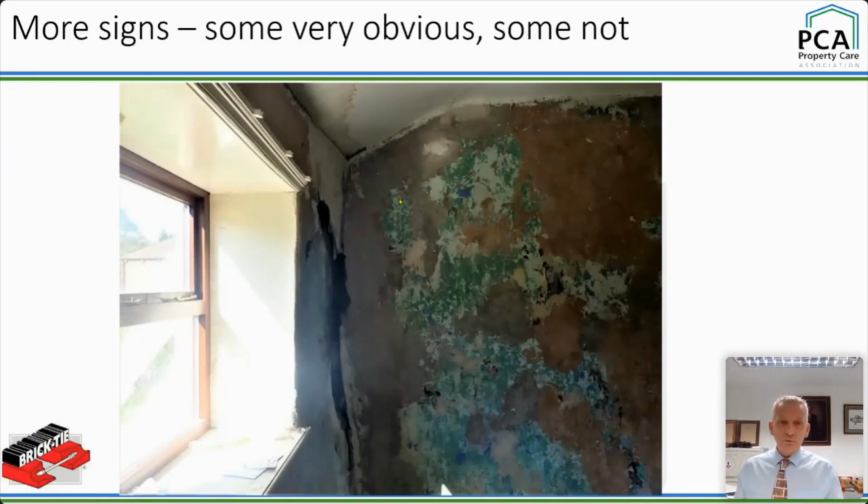Now, the reason I include it is often when we're surveying cottages and old stone buildings, they'll be beautifully decorated, bijou residences, right? And you'll see a concave profile there. The wall has moved, but there's no crack because it's been filled. And the question then is, has it just been filled, or has something been done to mobilise the mass of this wall to hold that back? A repair of the bond. Loads of ways of doing that.